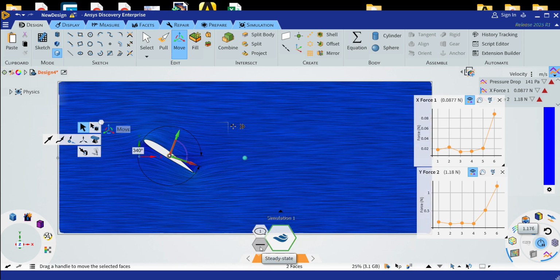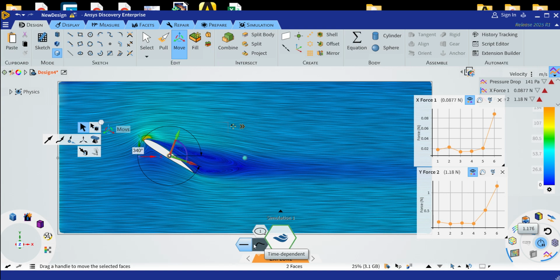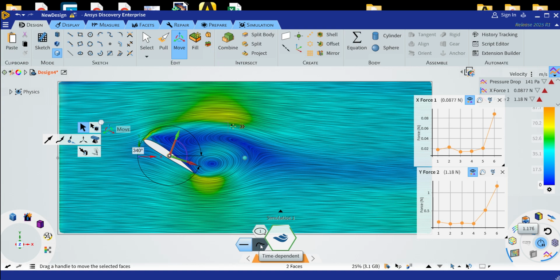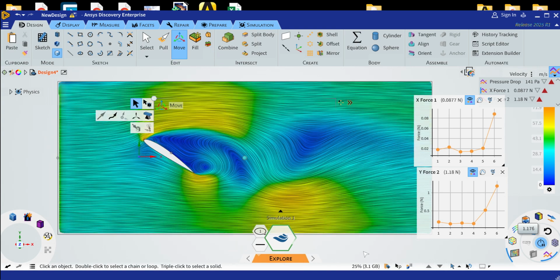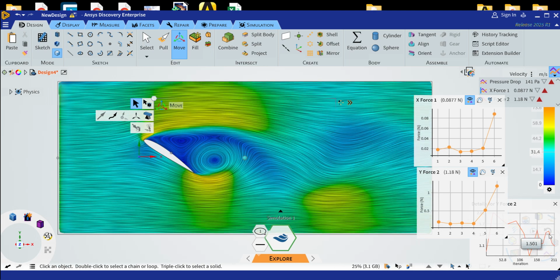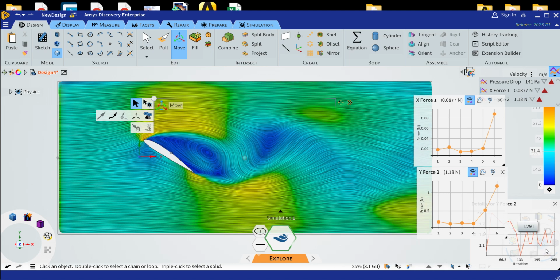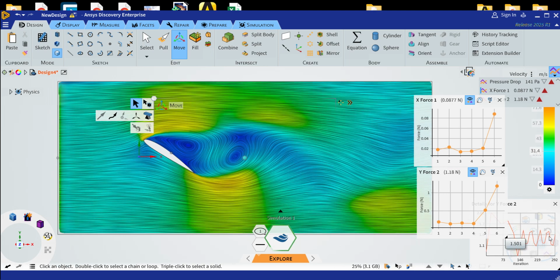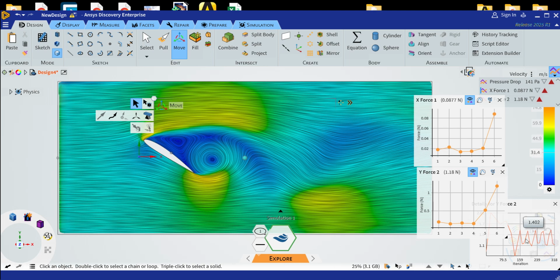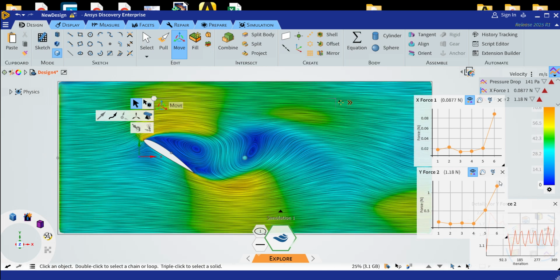So as I mentioned, even after 5 degree itself, you can go for the unsteady time dependent study. You can do it. Just by pressing this, you can convert steady flow to unsteady flow. And see, for this unsteady, if you see the instantaneous force, there will be fluctuations, but this fluctuation also will become constant. That is, the maximum, minimum, mean line, if you draw, it will be like a constant. Once it reaches the constant, the solution will stop and that mean value will be recorded here.